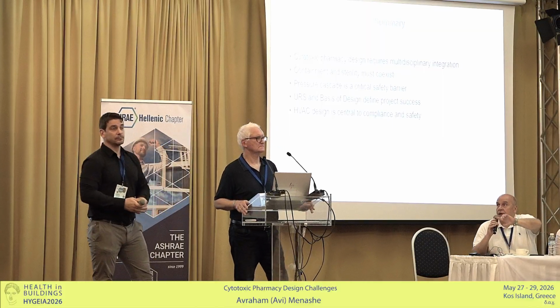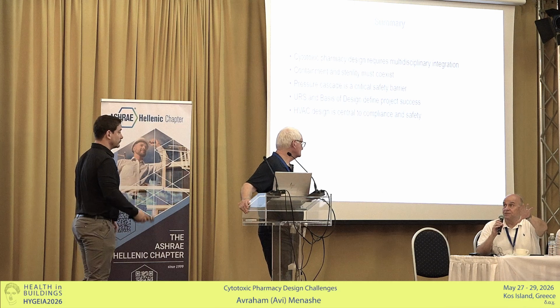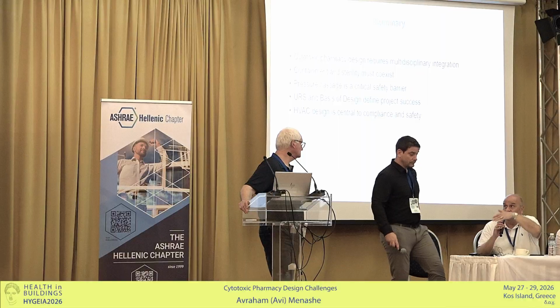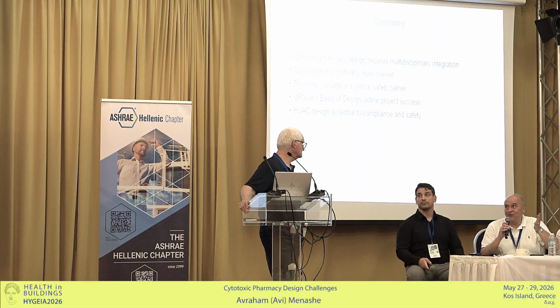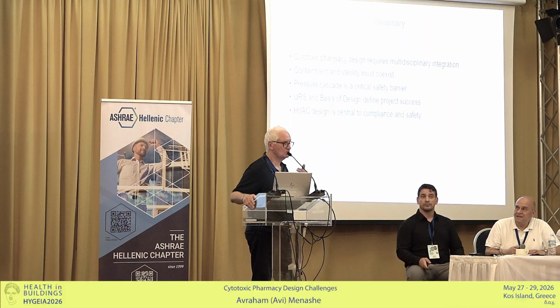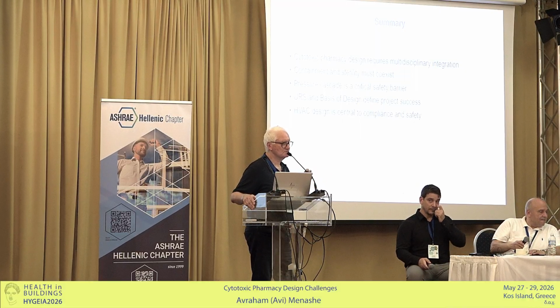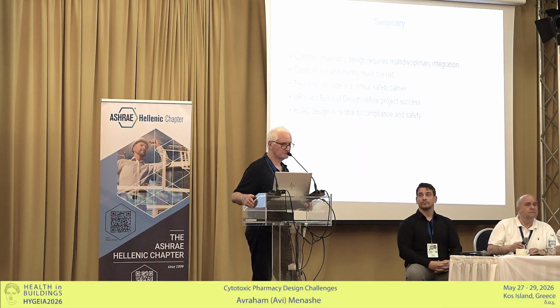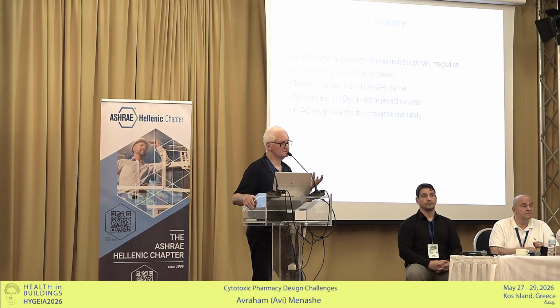A quick one, Avi: from your experience in the hospital, what has been the most challenging area that engineers usually have the greatest challenge with? Everything relating to laboratories, pharmacies such as this, and all the diagnostic systems is very important, because, for instance, diagnostic machines or nuclear medicine today require very, very clean conditions and also very accurate temperature and humidity, because of the accuracy of the machine.